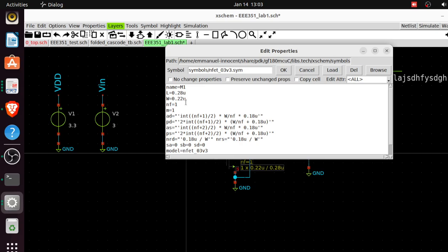a simulation thing here, but you can actually leverage on this in your simulation phase so that you can make things better. Many times the whole goal is to shrink, to have your whole IC be smaller. So instead of having a big device, you can divide them as if there are several devices making up one large device. Then M for multiplicity is more like a synonym of number of fingers, NF. They vary slightly, but they do the same work. But for now, we're just going to focus on W and L.